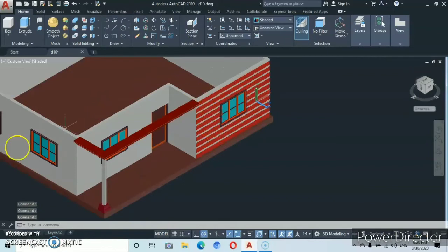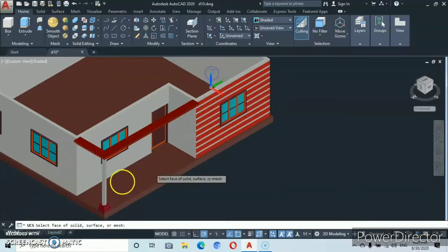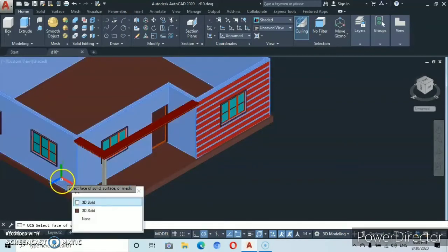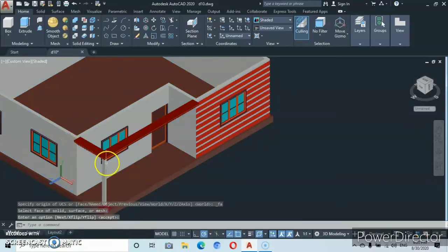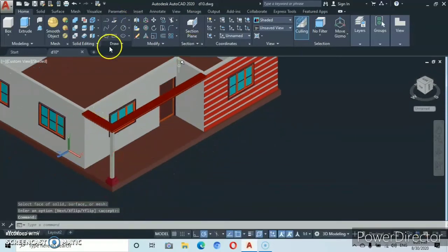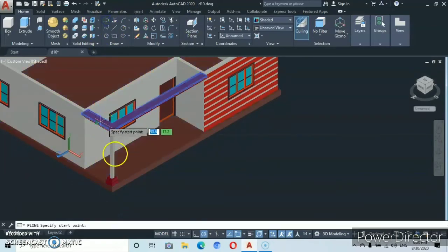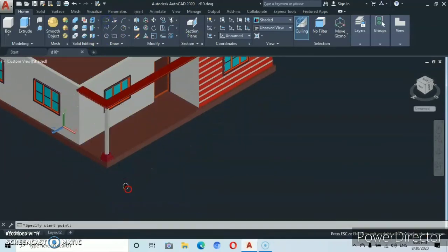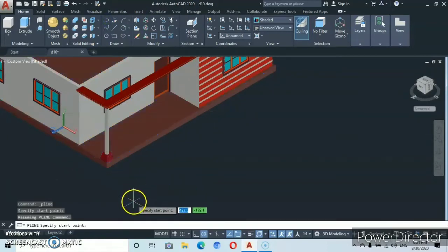So with that, I would like us to go to the coordinates and we take on face. Let's use this other face. Okay, let's use the other left face. Okay, we click on that face and let's select that and enter, because we're going to be drawing on this face. So let's go to the polyline. Then let's come here. I would like us to draw before carrying it to the wall. Okay, so let's type in a height of 30, 30,